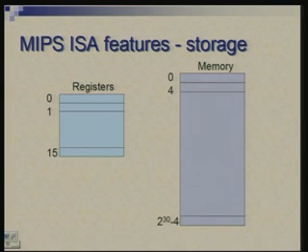One exception is register 0, which always has the value 0. You may use it as a source, you may use it as a destination, but its value does not change. It is ensured to be so by the hardware. And register number 31, which is used for the return address by the JAL instruction. Apart from these, there are no other exceptions, and any register could be used for any purpose. Of course, there are some conventions which are followed to ease the task of programming, particularly the procedure linkages. But that is a matter of convention, and given the same hardware, one could follow a different set of conventions.